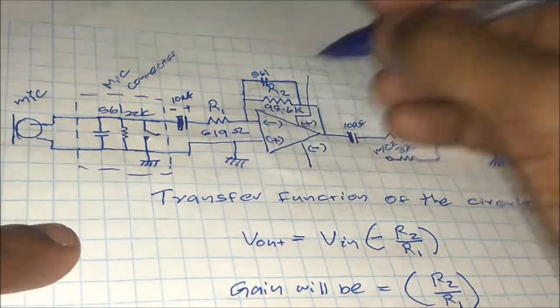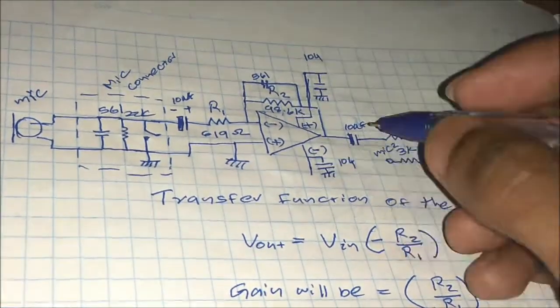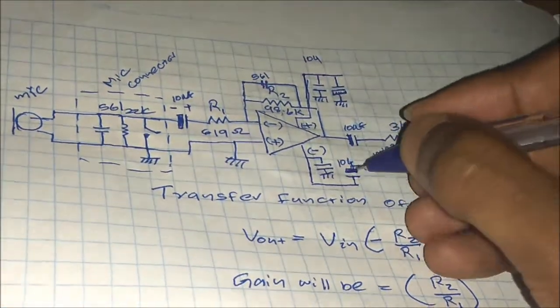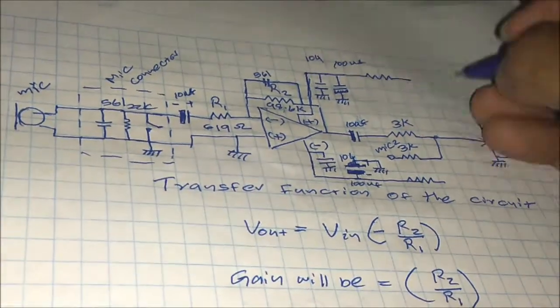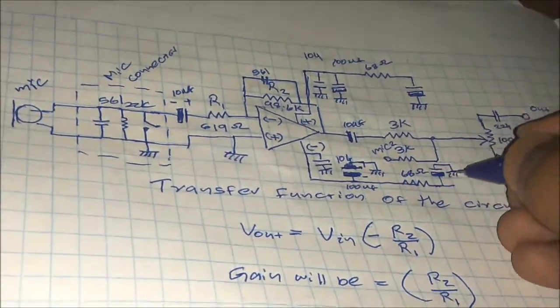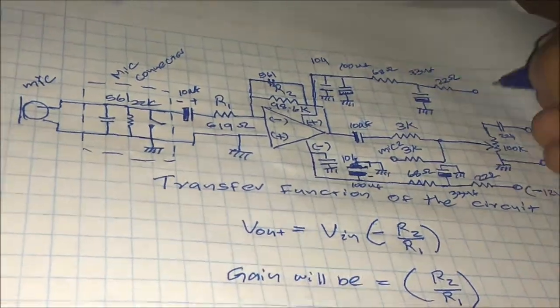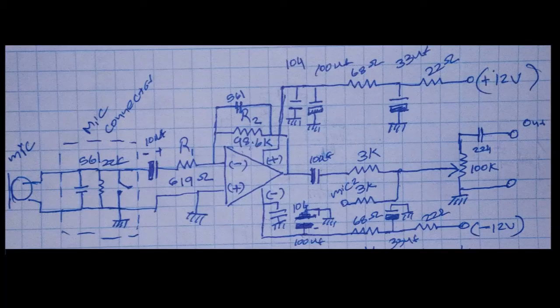For a smooth startup, I added another 2 resistors and capacitors to the IC power supply. Place the 104 capacitor much closer to the IC. Also remember to keep the physical distance between the IC and R1 resistor as low as possible. You can check the audio quality of this circuit because I'm using it to record the whole audio track of this video.